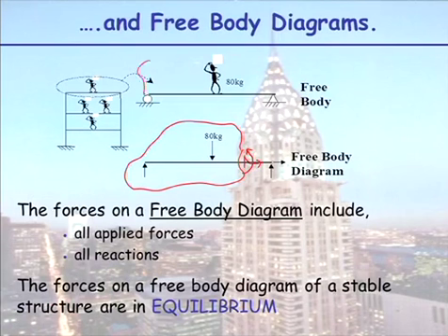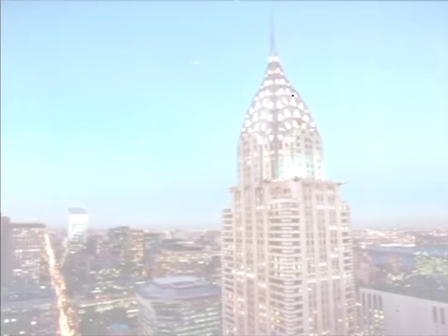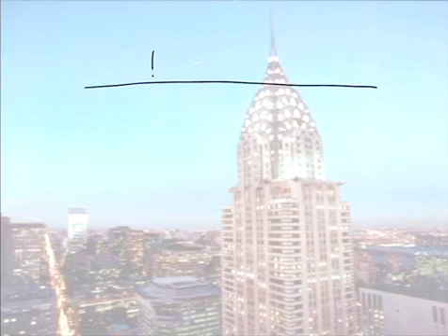Otherwise, what we did, in effect, we never drew it, but what we were doing is we were saying, okay, here is my free body diagram, and because the system isn't moving, it's in equilibrium, and over here I'm cutting through a roller that has one unknown reaction, and I'm cutting through a pin here that has two, and I'm going to balance those forces. I'm going to say it's not moving in space and calculate those unknown forces. So I'll set this question up, and I won't do it in its entirety because of our time constraint, but I will provide you with the answer.